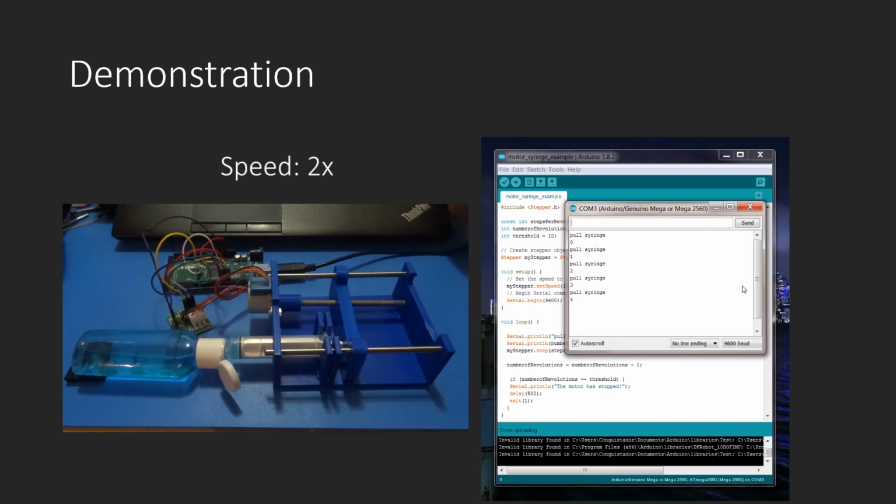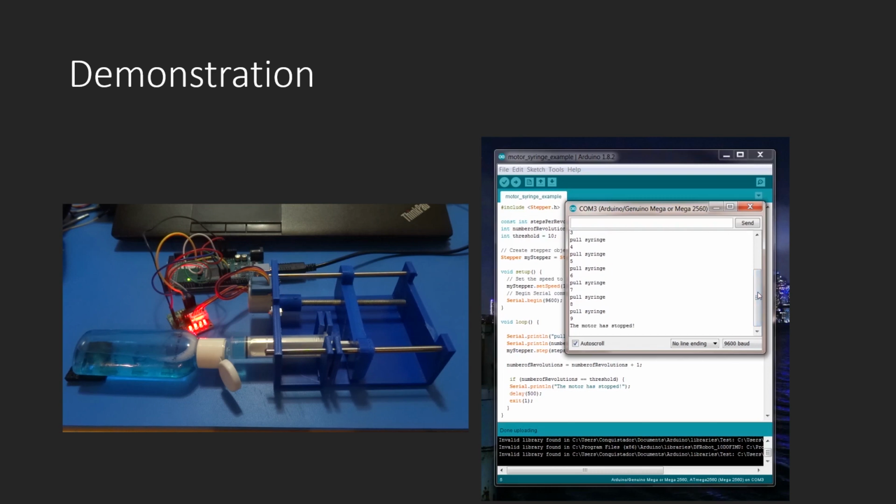Now, this project is still a work in progress and there's a lot of room for improvement. For instance, pushing the fluid back into the container didn't work well. Possible reasons for this are misalignments between components and the fact that the syringe is a little too far from the motor shaft, so perhaps I'll redesign this setup and post an update in the future. When you start building your own experiment, you'll have to do substantial ground testing to eliminate the risk of failure